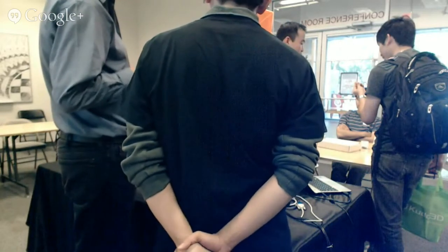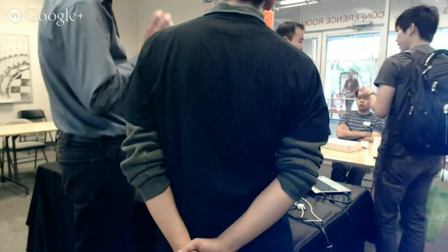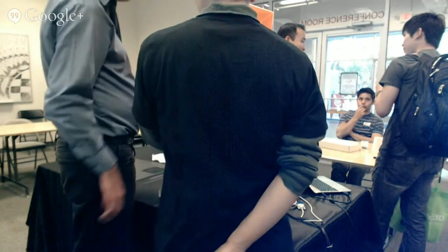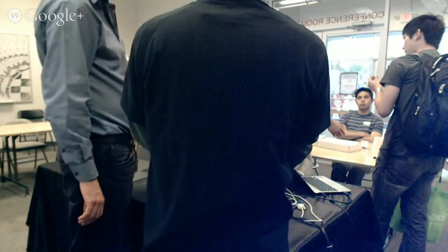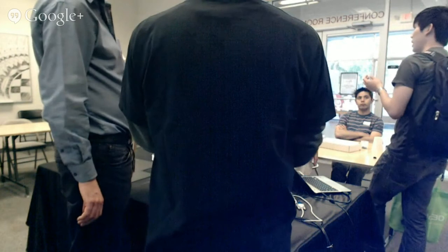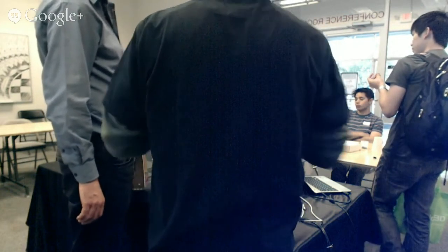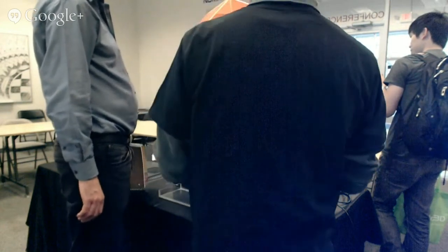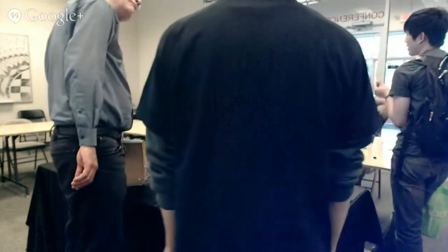And then suddenly I'm going to need supports coming down to make sure that this edge gets built. Because when I tilt it this way, I've got a concave surface. This part will start printing in Z before its base is formed, and that creates all kinds of problems. That's why eventually I couldn't get a good way of printing it like this. Plus, the flatness doesn't work out. And that's why I ended up printing it sideways like this. But if it's a lattice structure, lattice structures are very, very resilient because your per layer surface area is just so low.